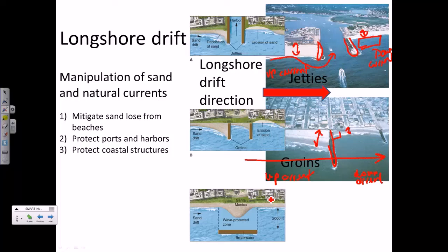The third thing we do sometimes is to put in what's called a breakwater, and the breakwater is shown down here at the bottom. Here it is. As one might expect, if we have everything perpendicular to the shore, now we're going to just turn something sideways and have it be parallel to the shore. So the breakwater is parallel to the shore. And what it tends to do is cause waves to get bent around and to come around like this. So the breakwater actually deflects waves around it and sort of brings them towards each other.